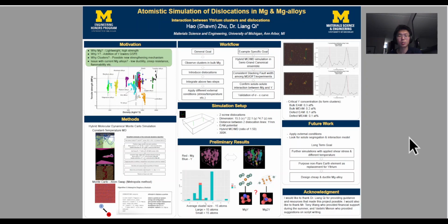From a kinetic perspective, these dislocations can facilitate plastic deformation by reducing the energy barrier and required stress to propagate the plastic deformation. So what is screw dislocation? Well, they can be understood by literal meanings, where the structure simply rotates with respect to a slip plane, leaving some of the atoms with higher elevations than others.